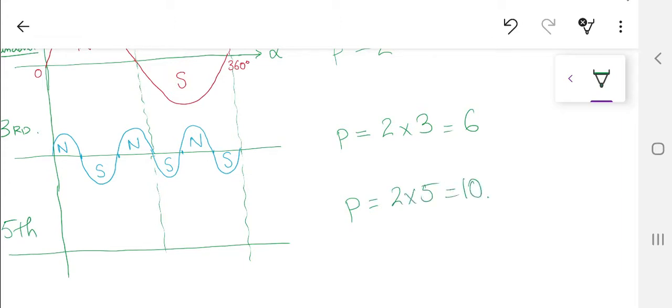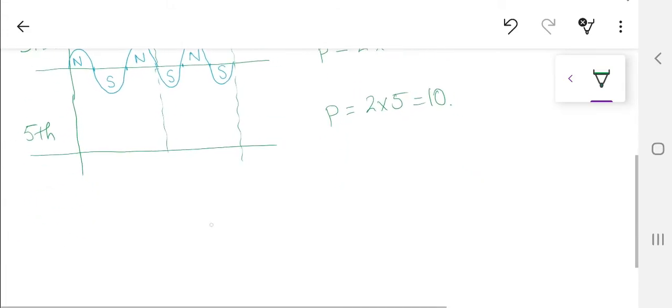Now this is very important, that by increasing the harmonic number, the number of poles which you are creating increases. Now the important point is, when the poles are increased, how is the speed of those harmonics changing? I'm not concerned with the speed of those harmonics, I am concerned with the magnetic field that is being created because of those space harmonics. I'm still in the stator or in the air gap at present, I have not gone towards the rotor and there is no induced EMF taking place. I'm not talking about that stuff over here.